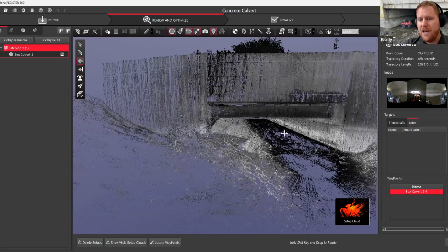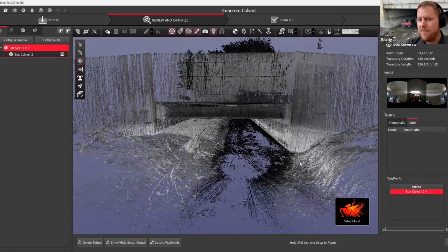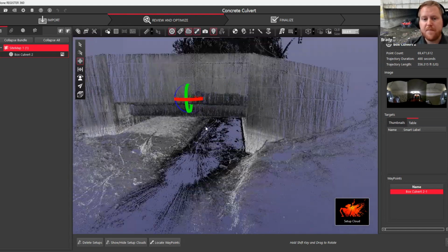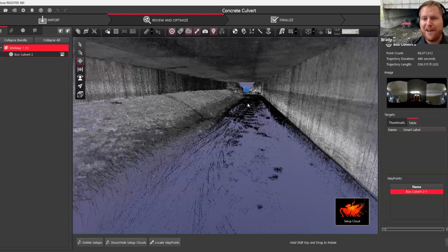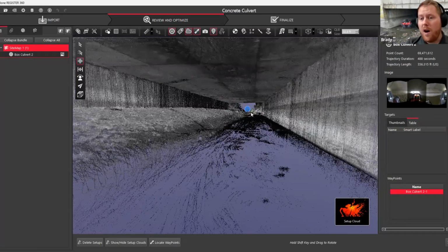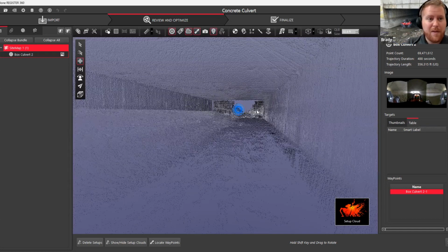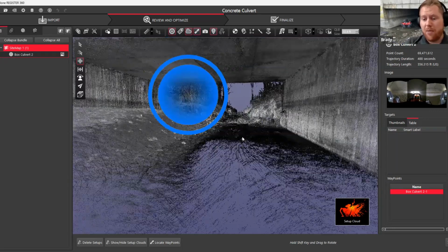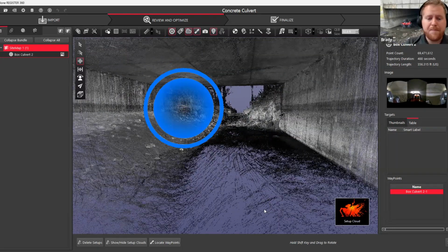And as we come out the other side, we basically walked out and walked back through it. So we captured some of the side retaining wall data where the road basically passes right over the top of this, so a very small little bridge. So amazing data comes out of something that we were able to walk within about 5 minutes. So let's get it up, start scan, walk it down, walk it back, and then we go back to the office and process this data within something like Register 360, and then we can do different analysis through different types of programs, such as 3DR.